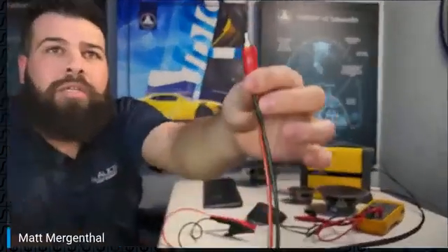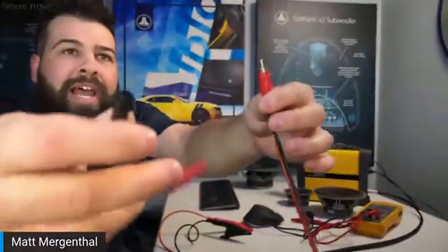Effectively, the difference between a 2-wire and a 4-wire is that in this case, both voltage and current are measured through the 2 wires. Whenever current flows through a pair of wires, you have voltage drop. So that changes the measured data slightly. So what we're going to do is have this other probe here, which I'll show on camera. It's an RCA on one end, and the other end is banana clips.